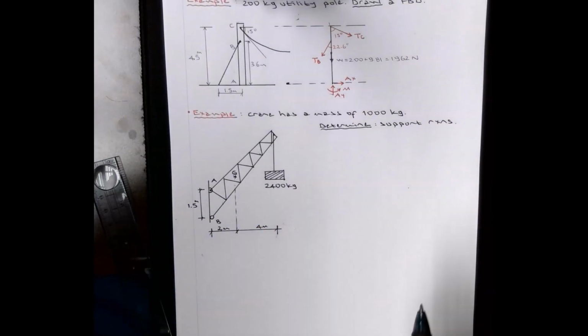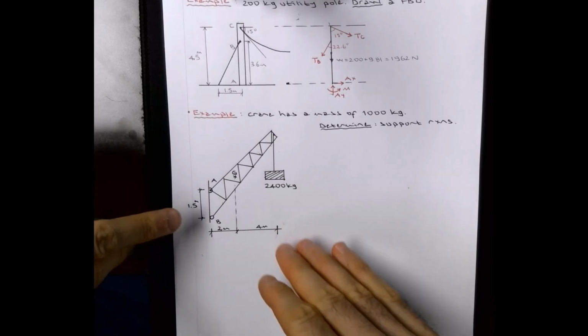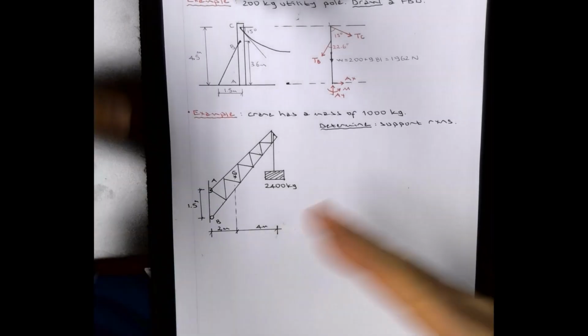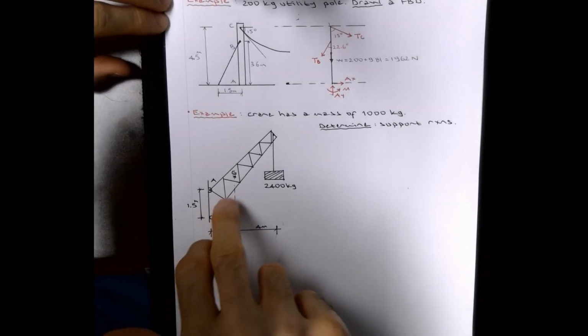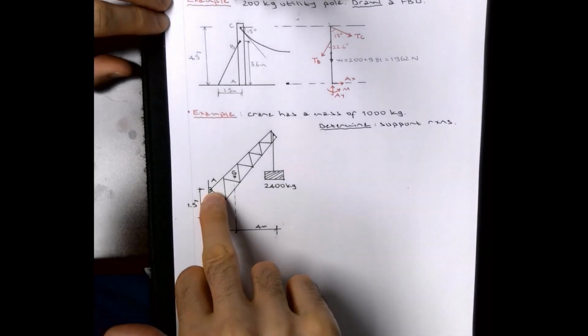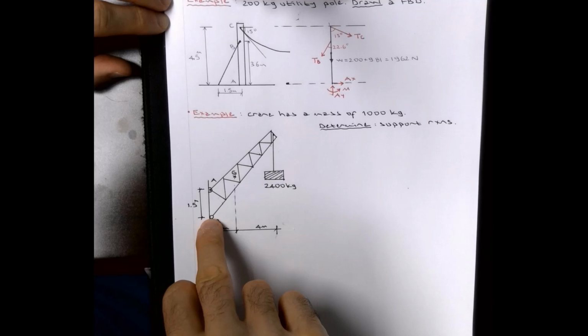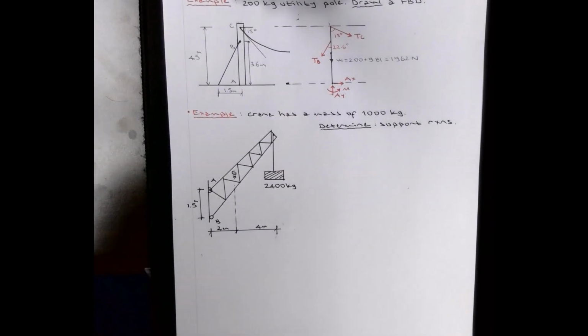All right, so we did similar questions in class. The first step is to determine how many unknowns. As you know, 3 is the maximum number. We are using statics. This is statics. So A is a pin support, so if it's pin, you are going to have 2 unknowns. B is a roller support, so you are going to have 1 unknown, so it's 3 unknowns in total. So what you may want to do is to sketch a free body diagram for this, right?